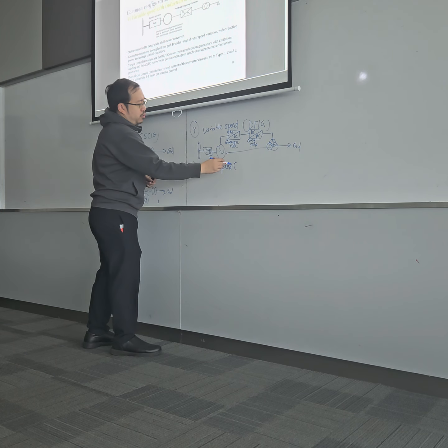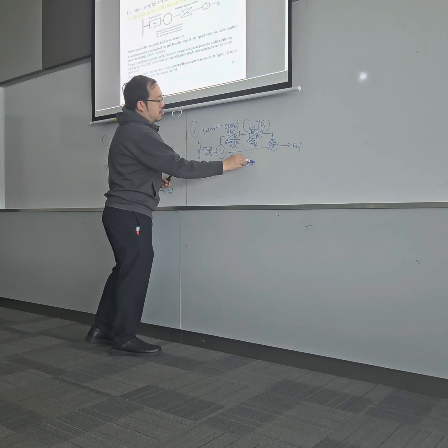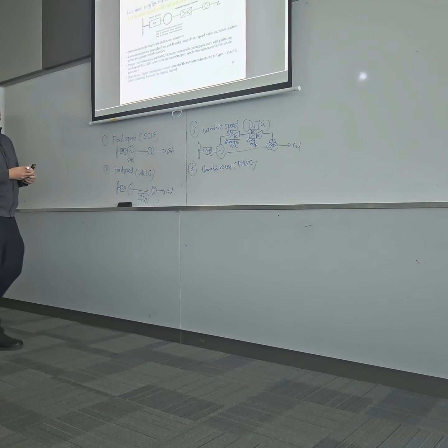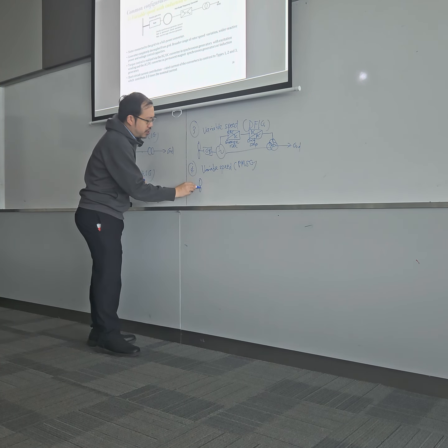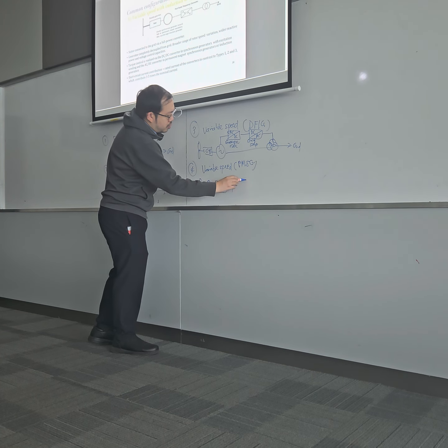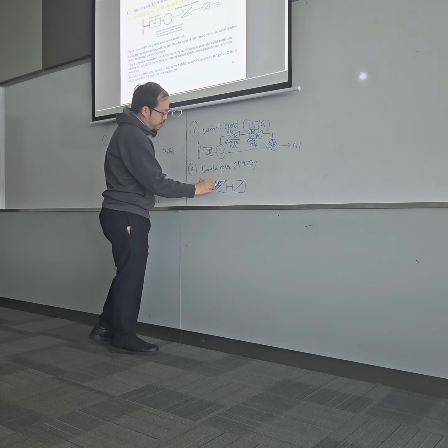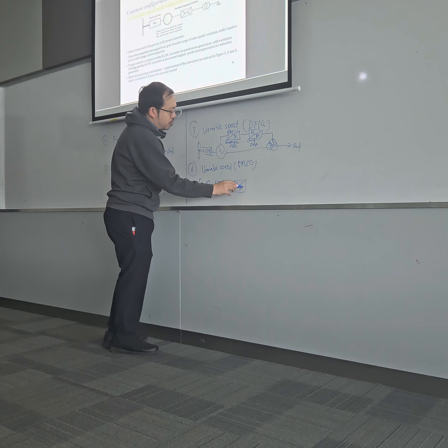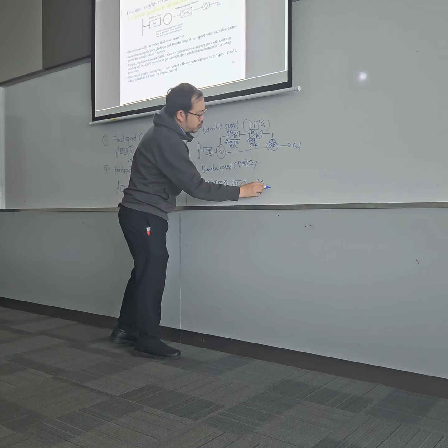So this one I will call it PMSG. It's not written here. Usually this is a permanent magnet synchronous generator, but there are also other forms of this Type 4. For a permanent magnet synchronous generator, the difference is there is no gearbox, so it's directly connected to the generator, followed by a back-to-back converter, and then to the grid.